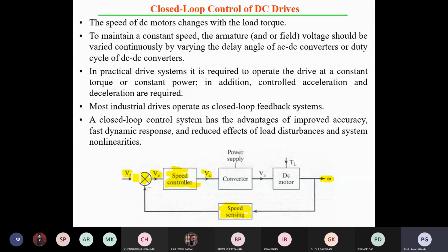Of your control signal. If the control signal is varying against the triangular wave, the pulse width also changes. Try to realize the problem. By the variation of the pulse width, the switch on-off time also varies.